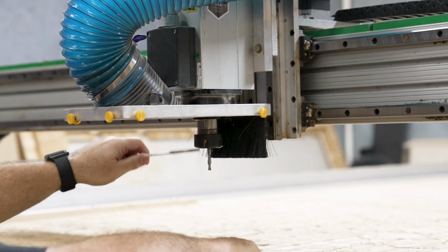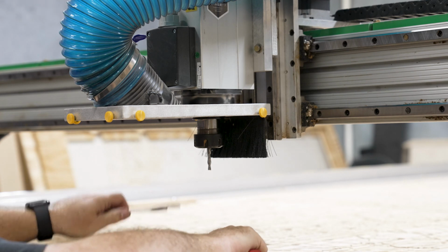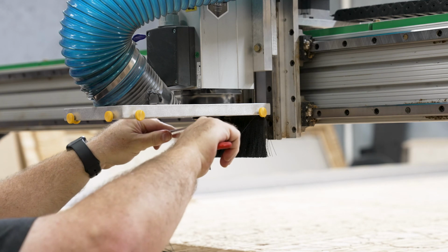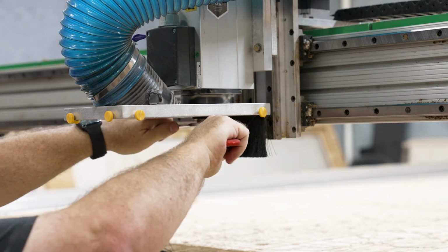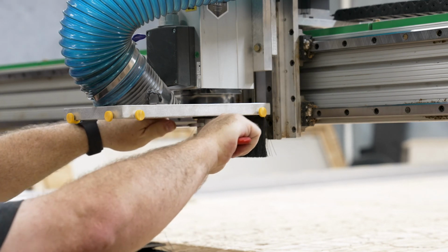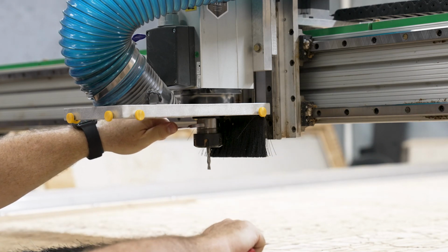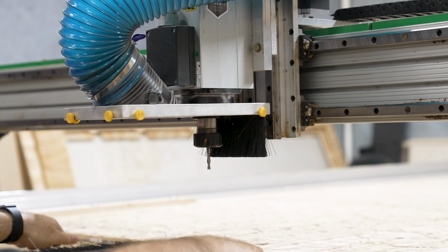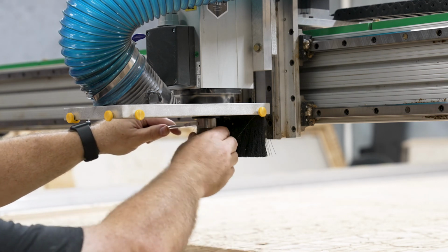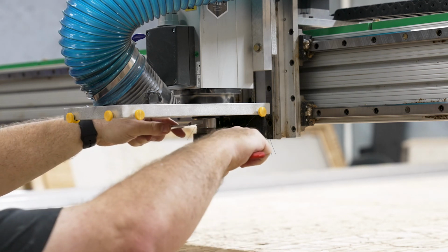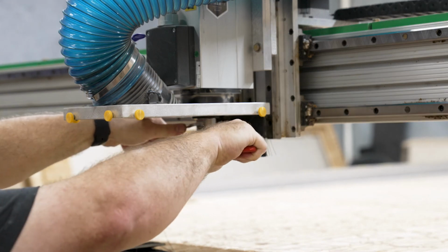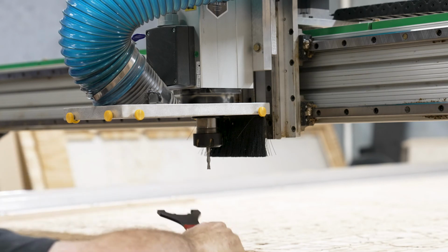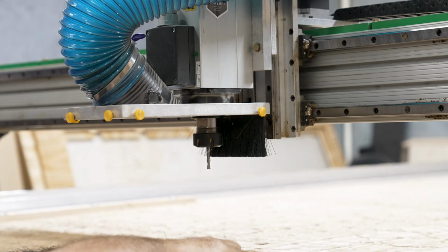Now, people ask, how tight does it need to be? Well, you don't want to put it on so tight that you cause the gantry to move. I mean, you can get on here. So Ron is a big man. He can get up here and put a lot of force on that would cause the gantry to move, which if the gantry moves, you're going to have to reset the machine's home position. So put it on tight, but also tight enough that you can get it off, because you're going to end up going in the opposite direction to loosen the nut.